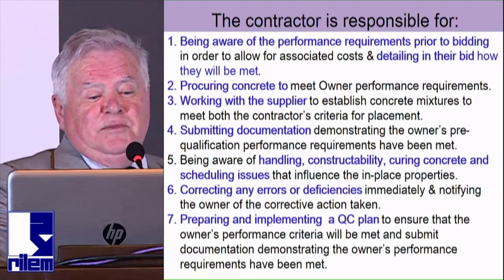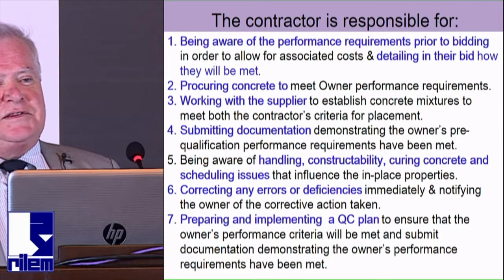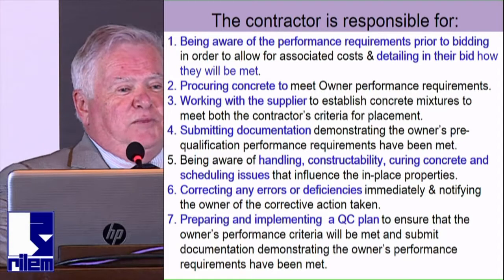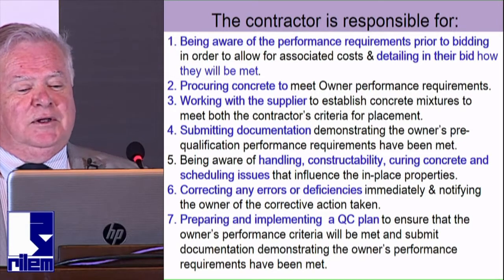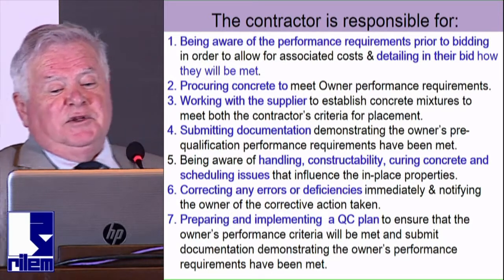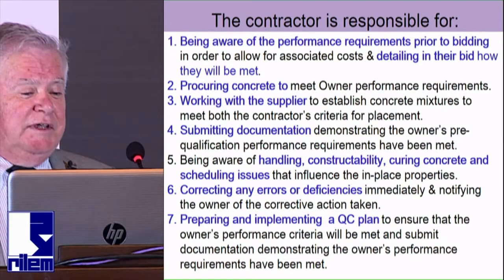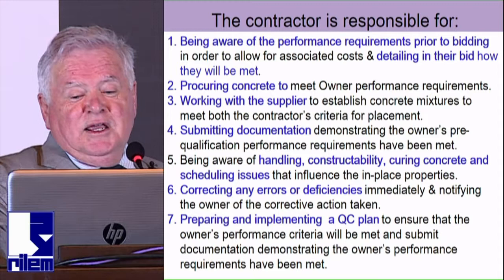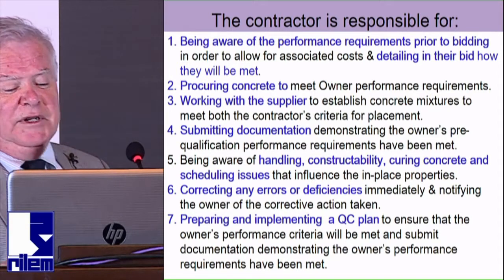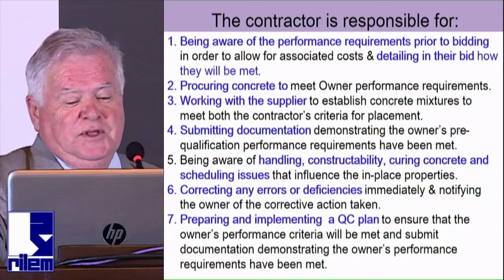And they need to work with that supplier to get the concrete they need for the placing conditions. It should be the contractor that sets the workability requirements on a job, not the designer, because the contractor has to place it with the people and equipment he has available to place that concrete properly. And you've got to submit documentation to demonstrate that you've met the performance requirements by pre-qualification testing, which I'll talk about shortly, and be aware of the other things that need to be done, and implement a quality control plan to ensure that the owner's requirements will be met over the production of concrete.